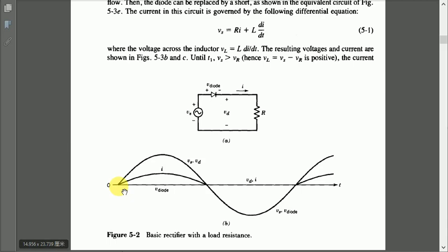And what I was emphasizing is that we need to take note of the current waveform as well. The current waveform has no lag or lead, that is, it is in phase with the source voltage. This is the current flowing through the resistive load, so it is in phase with the load. Definitely the magnitude is lesser than that. We'll see the equations in a while. During the negative half cycle, the current stays 0 and the voltage also stays 0. So you can see Vd, which is the voltage across the load, is 0, and the current across the load is also 0.